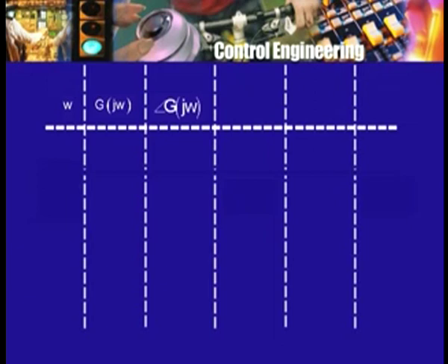And of course, if you are doing an experiment, then this is what you will start with. You will prepare a table like this, say omega equal to 0.1 hertz, 0.5 hertz, 1 hertz, 2 hertz and so on, maybe going up to 10 hertz or 100 hertz. Corresponding gain, in fact you may even have two columns, input amplitude may be kept constant, output amplitude, then gain, then dB gain, phase shift. So, this is the tabular form of the data. But from this it is very difficult to figure out what is going on.